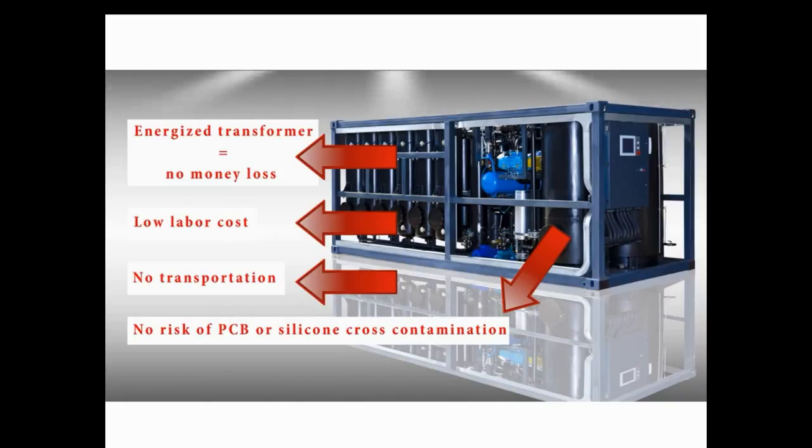Do you remember that today we have stressed we should start regeneration at 0.08 acidity? That's why, if we do an oil change, leaving 15% of old oil in the windings, very soon we will arrive at aggressive oil acidity. Surely we had to do oil changes sometimes, but we do have an alternative now. To regenerate oil after 10 operating years, it takes 1 day. To regenerate oil after 20 years, it takes 5 days.